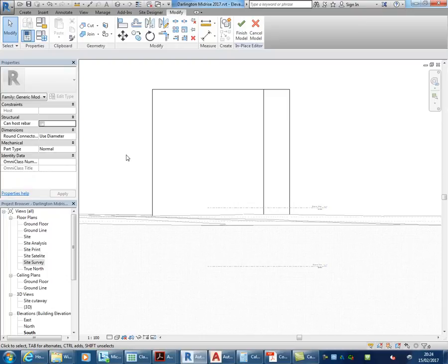Yeah. Move it down below all the other levels, give it a new name, and then make a new level and call it ground floor, and stick it in between level 1 and your basement. We did make some other 2 basement levels, so we can then move them up above it. Oh, you can leave them. So leave them where they are. Leave level 1 that's above your basement, and just move that ground floor level out below, and then make a new level for ground floor after you've renamed.